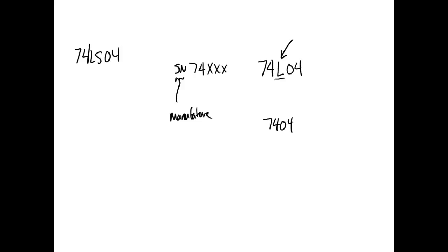So these are pin outs, right? You understand? Is that a 7404? Is that a 74LS04? Is that a 74ALS04? Is it a 74HC04? A 74C04? The pin outs are all the same, because those middle letters do not change what it does, what type of gate it is and how it's wired. All it changes is the power characteristics of the thing.